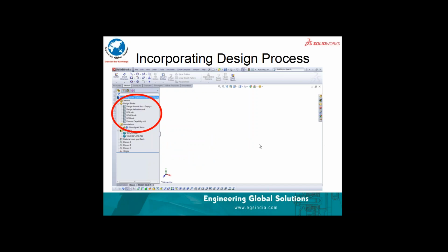Now, incorporating the design process. When we look at incorporating the design process, you are looking at the all familiar CAD interface over here. You see the design binder in which you look at the design journal which comes up with the design specifications and the calculations. And then you have the design validation document, the design for assembly document, design failure modes and effects analysis, design for Six Sigma if you are looking at quality beyond conventional designs in terms of tolerances or in terms of the processes. And last but not the least, the process capability that exists in our shop floor or in our supplier's place. When we incorporate this as a part of the assembly document, we are intrinsically integrating the design process that I have shown earlier so that good practices in design come about. How good is my design in evaluating ourselves versus these best-in-class practices.